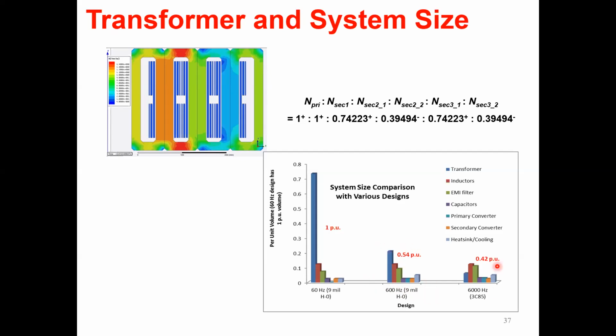If we go to a higher frequency transformer, this is a ferrite core material with 6 kilohertz frequency. Because we are switching at higher frequency, we need more cooling and better EMI filter requirements and so forth. In terms of size, of course, it is smaller than the medium frequency, obviously, but is it worth going to a much more complicated design, as we saw earlier?